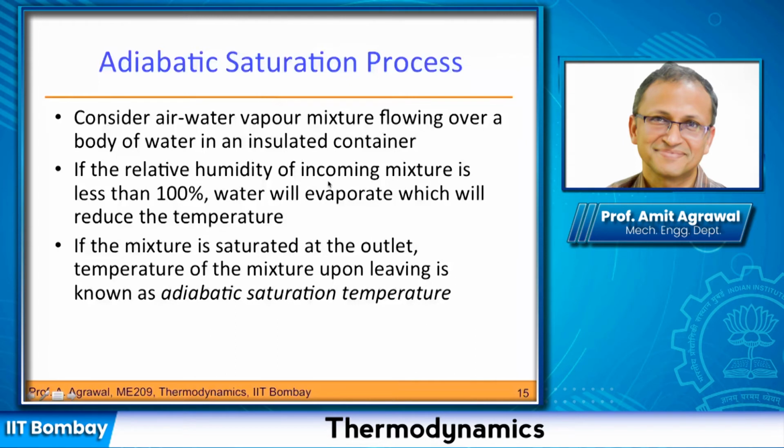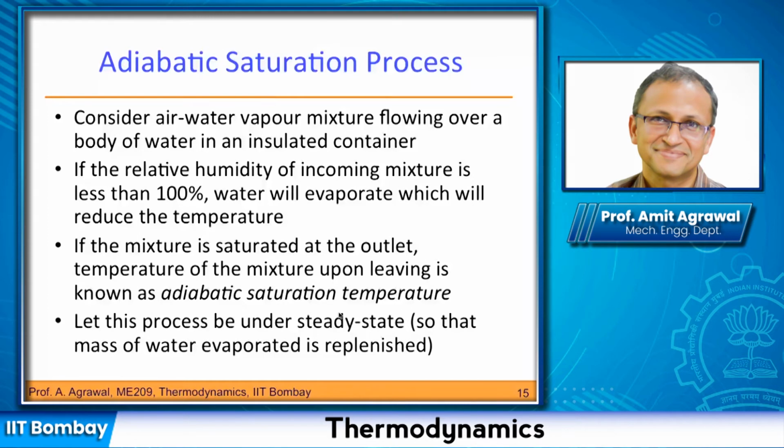It's not an assumption. If we have to actually do this process, then we'll have to ensure by design that there is no heat transfer or minimal heat transfer happening. Then we can define that whatever is the temperature of the air which is now leaving my control volume, I will call that the adiabatic saturation temperature. It is essentially happening only because of the mass exchange between the air and the water pan that you have.